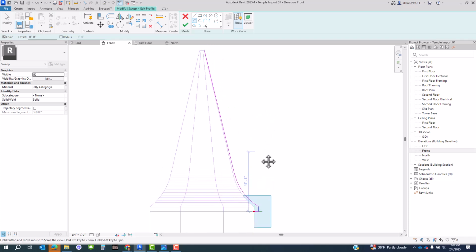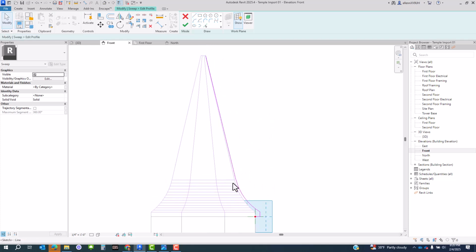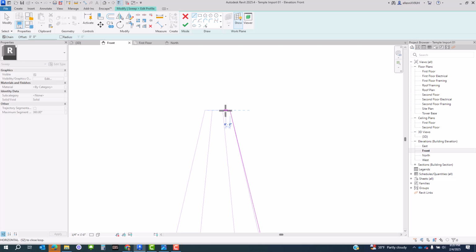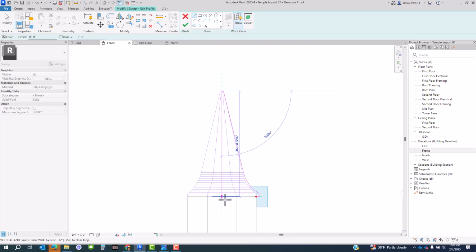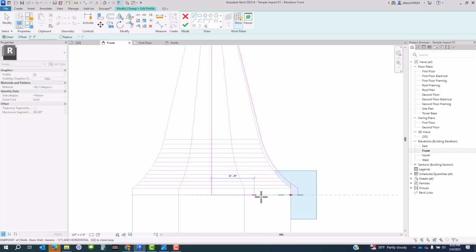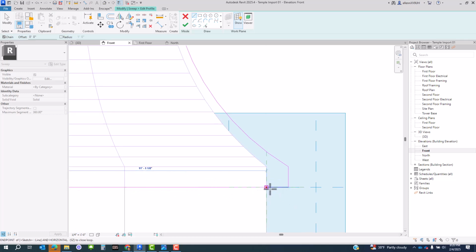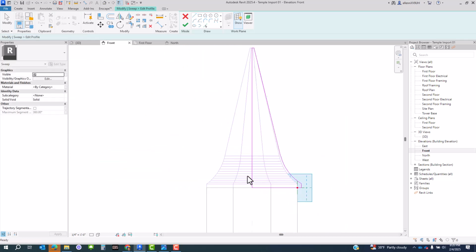Okay, and it's not a shape yet. It's a nice outline of the roof, but it has to be a fully enclosed shape. So I'm going to draw this back towards the center, and then all the way down to the bottom, and then back out to the end. And be careful, because I already drew a small segment. You can see it highlighting there. And if this new line overlaps with the previous line, it's going to be a problem. So I need to just go back to the starting point, and I should have a profile.